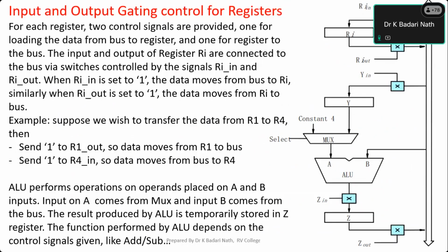It is like an open, which means a disconnect. It is a high impedance state. Most of the ICs or buffers have this capability. They are called tri-state buffers. They have a normal 0, a normal 1, and one more state called tri-state, the high impedance state. So this is called a buffer.